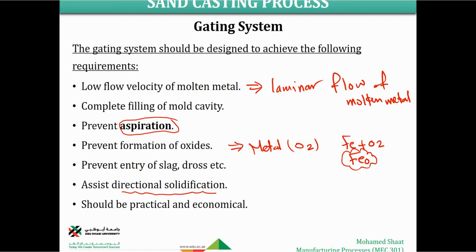It means that we have to have the same rate of solidification through all the material to have a consistent material. As you remember, we discussed here in the manufacturing class that we do have the heat treatment processes. Heat treatment means that you heat the material to a certain temperature and allow the material to cool at a certain rate. So the rate of cooling down the material is a big deal. The rate of solidifying the metal is a big deal.